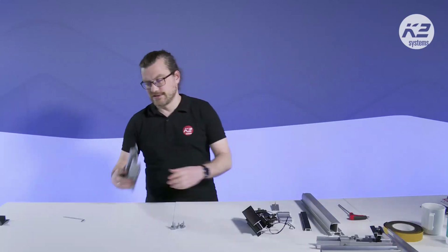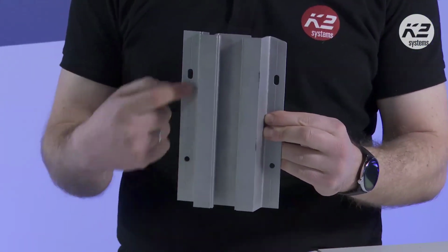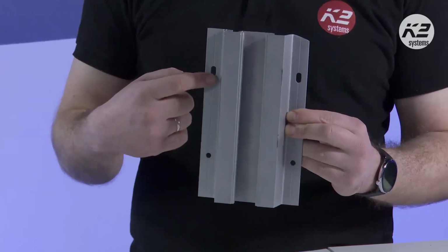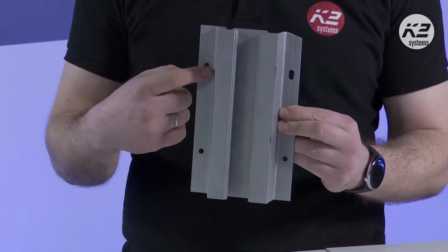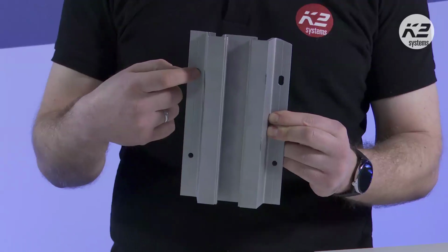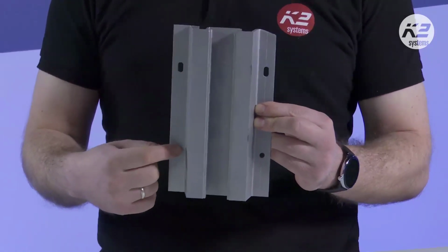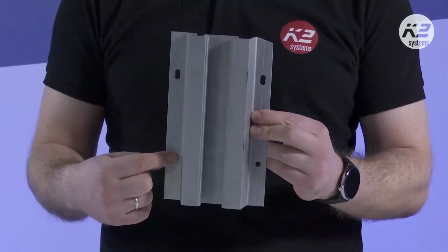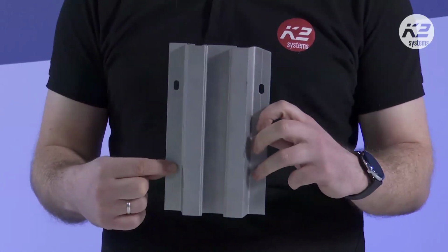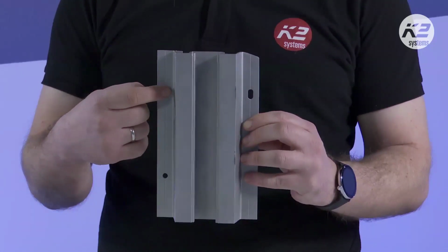And this CarrierRail has two types of holes: round holes and slotted holes. Round holes are for the fixing bearing and slotted holes for the floating bearing. What does it mean? It means that the rail fastened by these slotted holes, the floating bearing, can extend up and down. The round holes for the fixing bearing are used only somewhere in the middle of the rail. You will only use 2 screws for the fixing connection, and all further screws will be used for slotted holes for floating bearings.